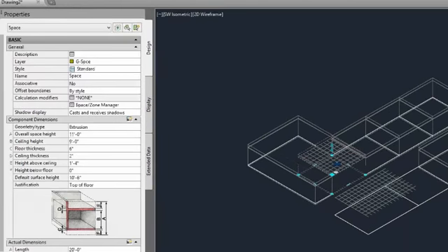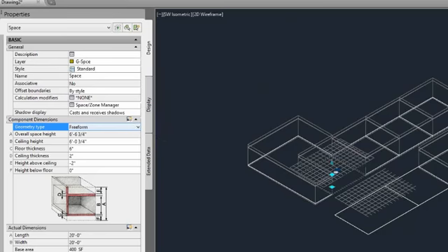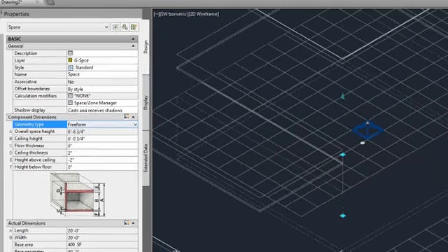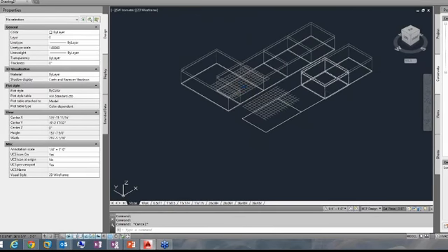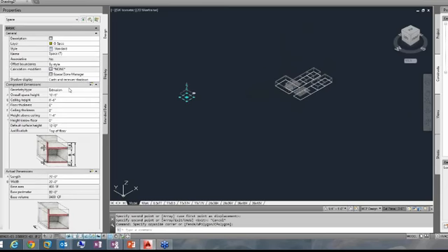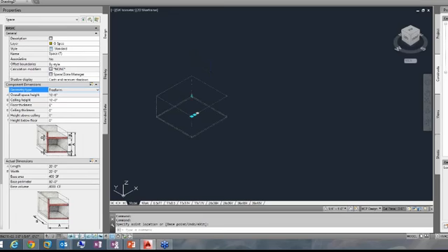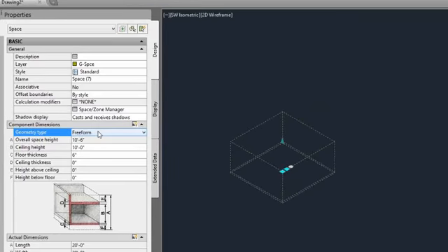Yes. So when I selected the space and we said geometry type, we looked at extrusion and we looked at 2D. What we did not look at was freeform, and that's the type of space that you would use, and it would allow you to configure that space to what you needed to do. If I copy this one out here in the open and just choose freeform, I would probably need to read up on it a little bit, but I'm pretty sure that that allows you to create it in any manner that you want. And it's probably something where you can create the geometry as a 3D solid,